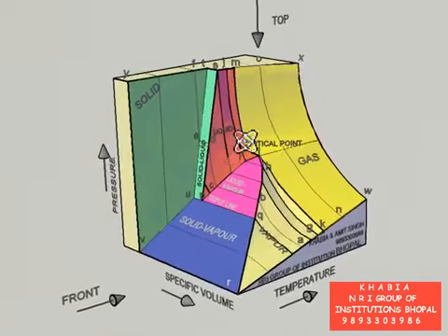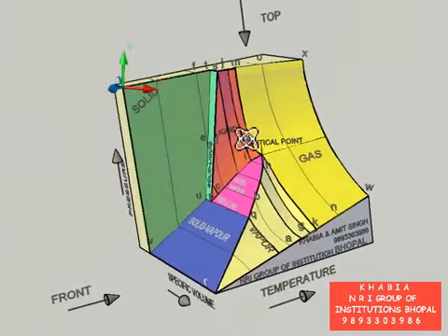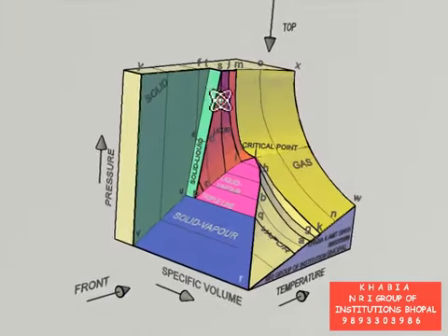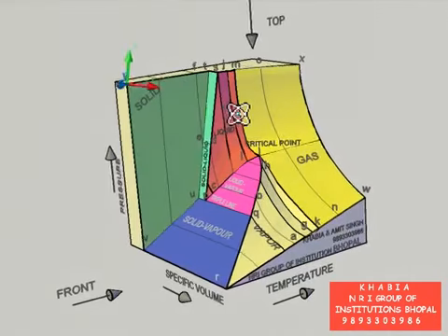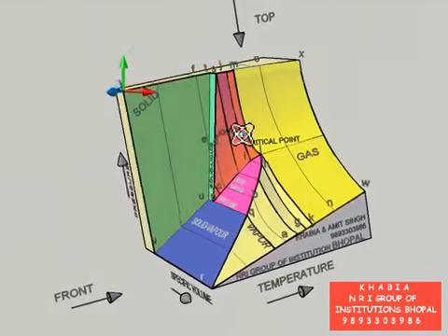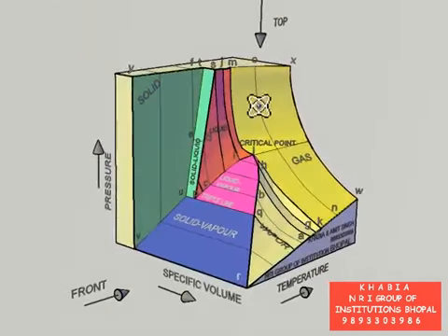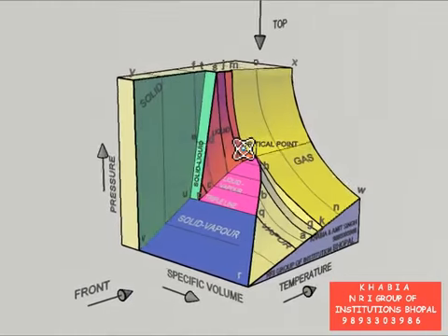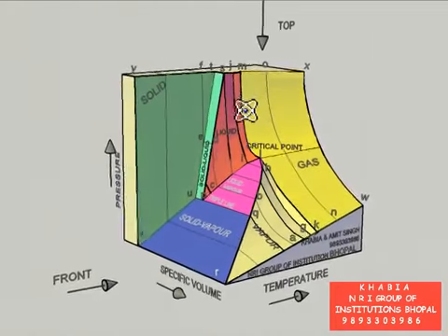One thing I would like to add here is that at pressures higher than critical pressure, the differentiation between gas and liquid should not be taken very seriously, because at pressures more than critical pressure, for a pure substance, liquid and vapor phase never coexist in equilibrium, and we can call the pure substance simply a fluid.